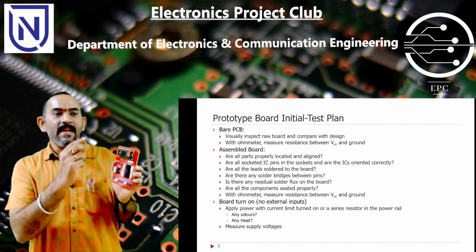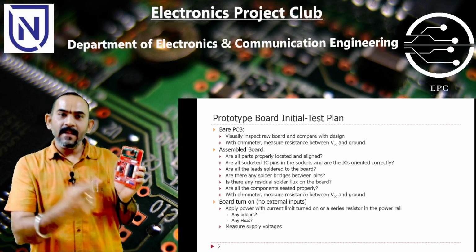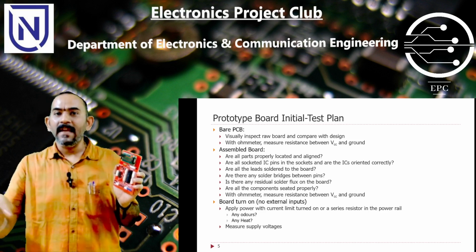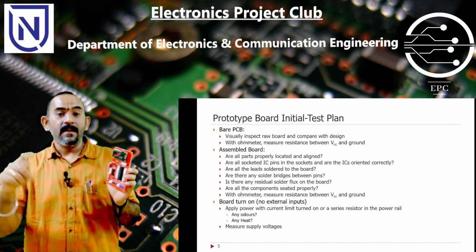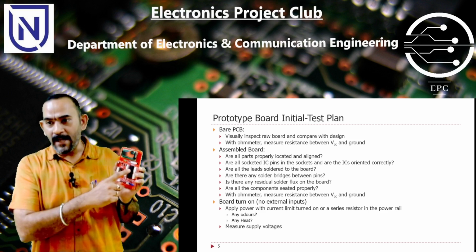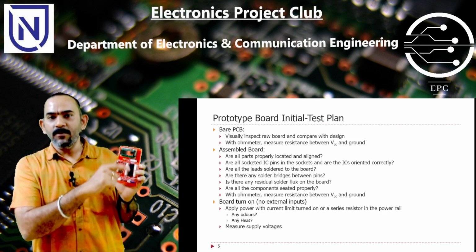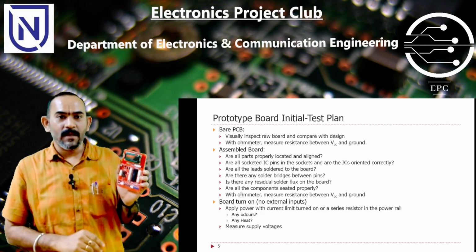Then to remove the additional solder on the pins, you have to heat it, then you put it in again, you have to heat. So you heat it, cool it, heat it again, multiple times, which may cause the component to go bad. That has to be avoided, but still this is a necessary step. You need to know if the components are mounted properly or not.